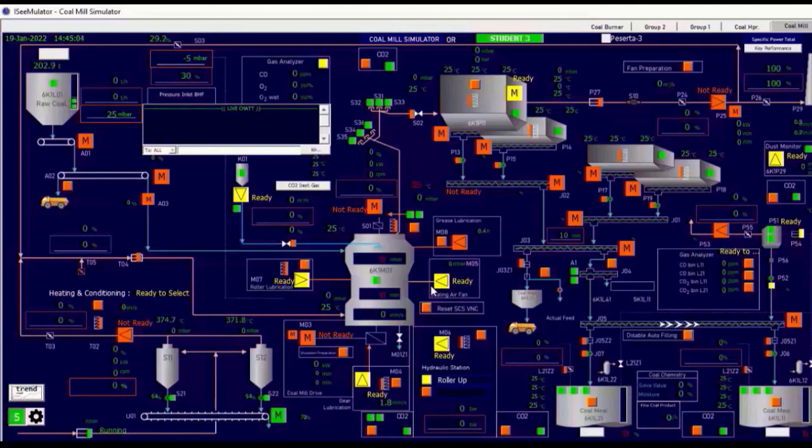Why? Because what is processed is fuel, and to operate the coal mill also uses hot gas. What we must always remember is that there are certain limits that must always be followed, such as for example mill outlet temperature limits, CO and O2 limits, fine coal product fineness limits. For example, to grind coal of low quality or low calories.